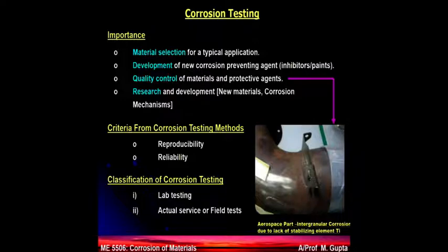For example, when you use a material in the marine atmosphere, you may need a different material. When you want to use a material in the dry condition, it can be a different material. And if you recall, if you have the sulfur containing gases, you don't want to choose nickel. But if it's a halide attack, nickel is no problem. So this is all material selection.